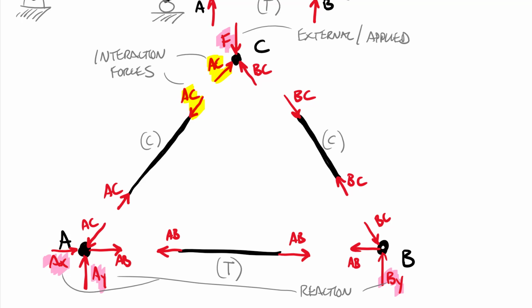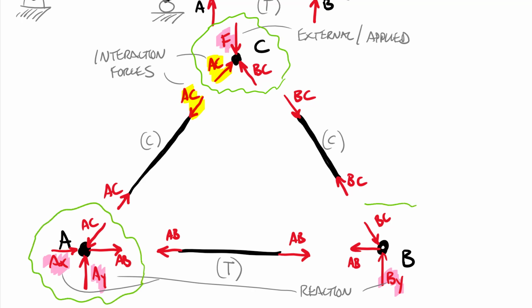All right, so in order to solve for trusses, there's a couple of different options. One of those options is to take a look at each and every joint. Each of these joints is a free body diagram. Now, these are concurrent force joints, right? So being concurrent forces, we only get 2 equations for concurrent force systems, just like we did in chapter 3.